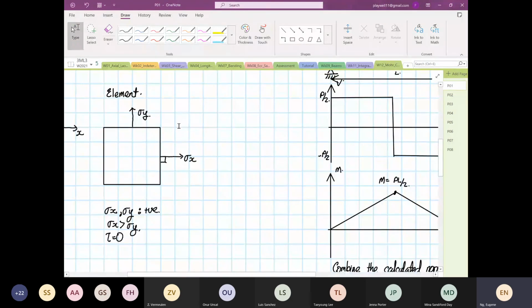So I'm going to construct Mohr circle now. This is Mohr circle. When I teach Mohr circle, we are not going to use the transformation equation. We are just going to draw the circle, because you can solve very complex problems by just constructing the Mohr circle, rather than using the transformation equation. The transformation equation is a black box. You don't know where you are.